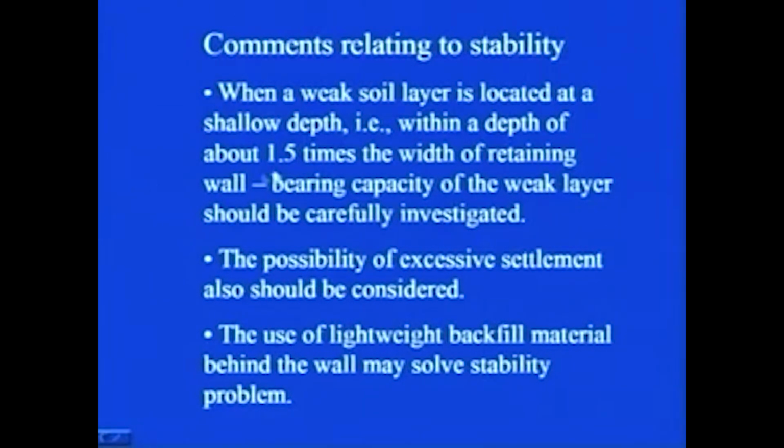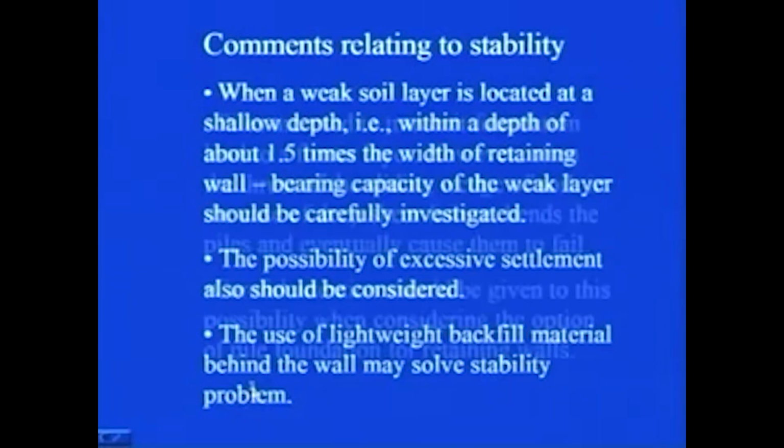Then, we have not talked of anything related to settlement, but that is an important serviceability criterion you must always keep in mind: the possibility of excessive settlement should also be considered. It may happen that the wall is safe against overturning, sliding and bearing capacity failure. However, the settlement can be quite high. So we should always keep that possibility in mind. The use of lightweight backfill material behind the wall may solve the stability problem. So that also is another option.